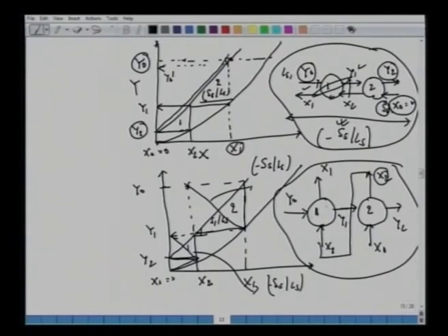In other words, this is the first stage, this is the second stage. Now we have put them as cross current. The two methods are the same and they must give you the same result. Starting from x0, we start from the first stage, we bring down to this level here, y1. Now we bring y1 in contact with x2 here, to bring back to the second stage where we have y2 and x2. So y1 and x2 are in contact here to bring back this concentration level at y2.